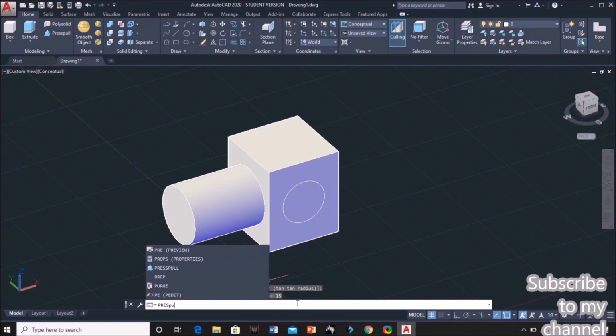So press pull is used to remove the object from a 3D solid object. Click on enter, then specify, select object or bounded area. So we need to select the area, that is the inner side of the area, to remove it. Okay, so I have selected the inner circle area.